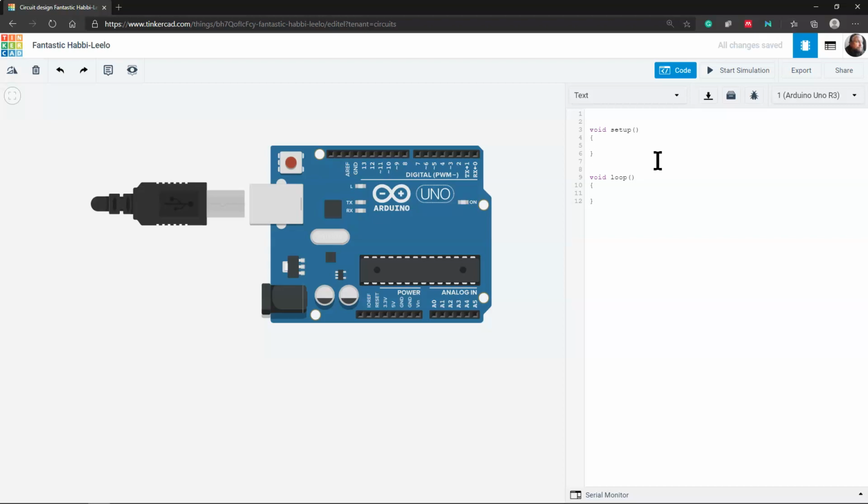Then it automatically calls the void loop for you, and then any code that's in here gets continuously run again and again and again. So whatever you see in here goes to the bottom and loops back up. And this is again going to be key for when we want to take advantage of that robot control loop. We're doing a closed loop, is this having it continuously repeat and do work for us. So we don't want to treat it like the main where you go from the first line of code to the bottom and then the program stops.